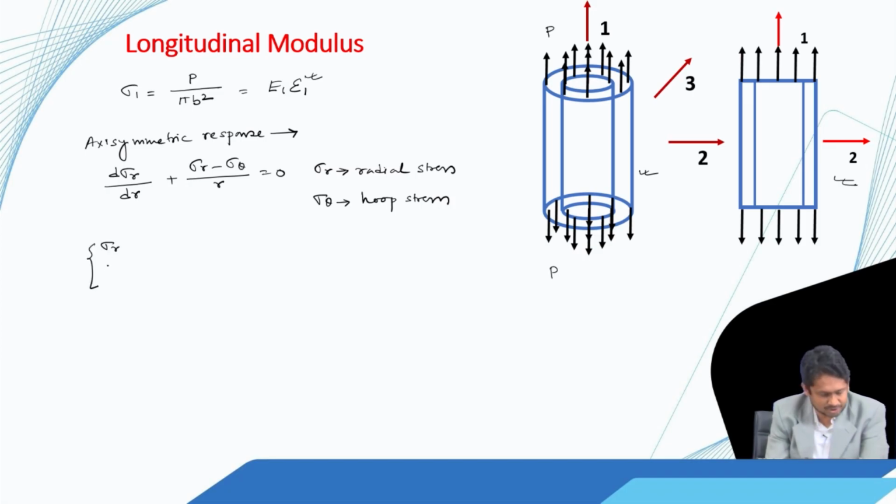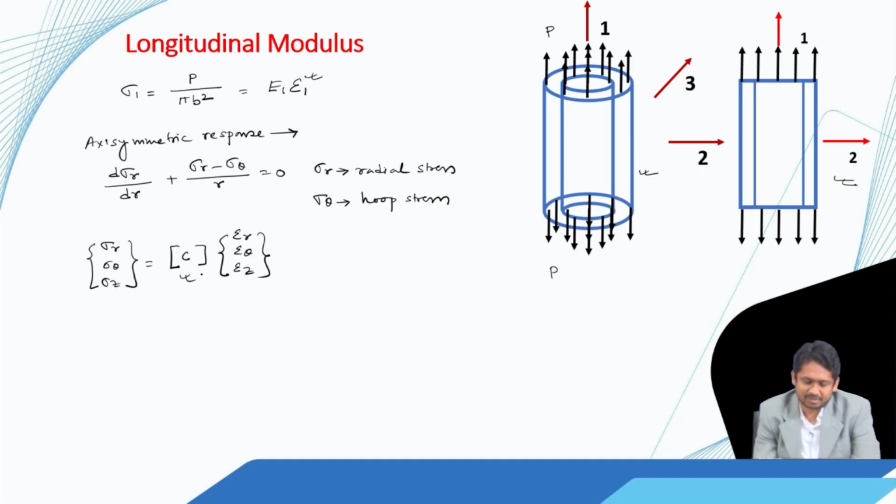Now, we need the constitutive relations, that means a relation relating the stresses with the strain terms. So, we have strain terms as this, and C is the matrix of the material properties. C is such that all the diagonal terms, which relate the normal stress with that same normal stress, are this.